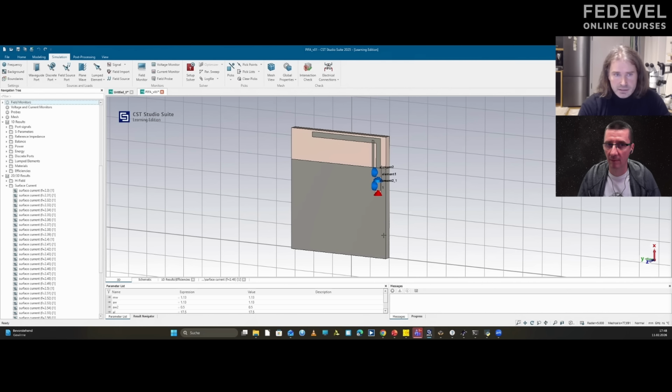So this technique is called characteristic mode analysis. And if you know the characteristic modes, you need only to excite them. It is not so easy as I tell you, but this is the way how you can make everything into an antenna. So if you have a PCB, you can make a PCB into an antenna.